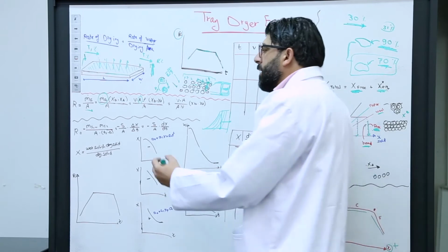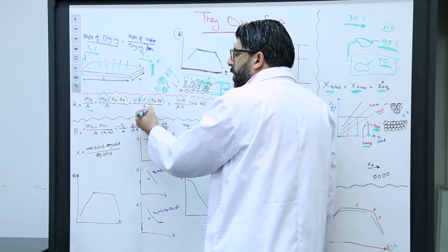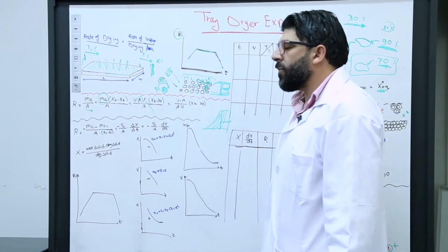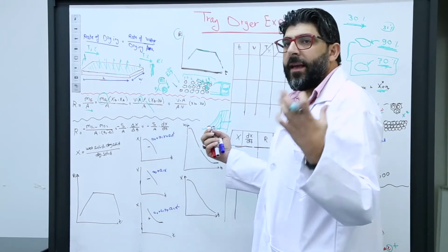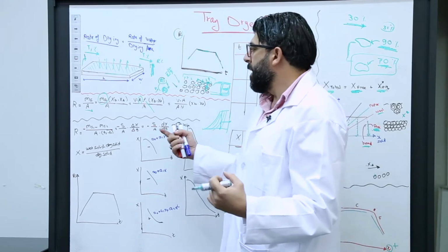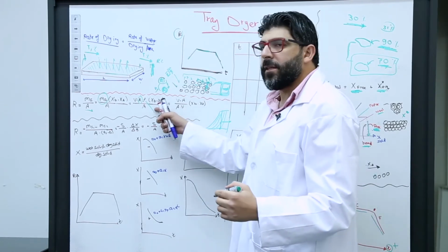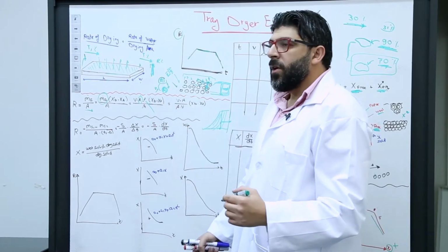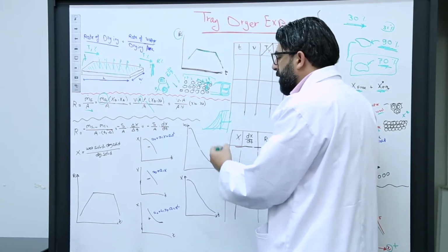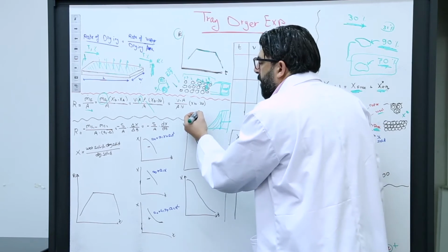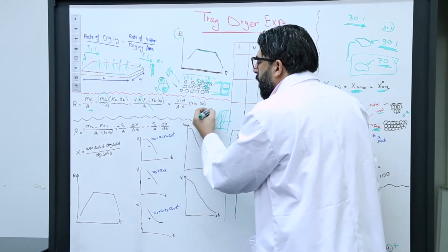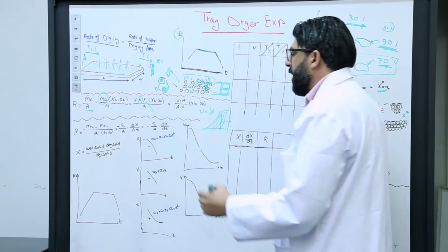You shouldn't calculate the density using the ideal gas law because it's wrong, but you have to, because the air here is moist air. That means the air has some water inside. So in order to calculate the density correctly, we use the psychrometric chart. From the psychrometric chart, we have something called specific volume, and specific volume equals 1 over the density of air.